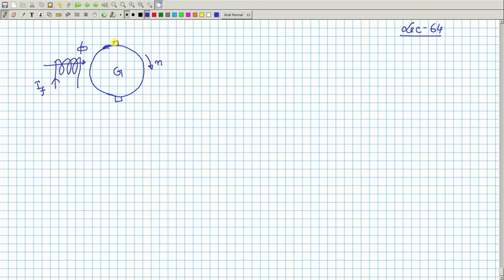Anyway, we found out that if this is rotated, in this case, the voltage across the armature terminals A1, A2 under open circuit condition, if I say generated EMF E g, it is given by P z by A phi into n, so much volts, if phi is in Weber and n is in RPS, do not forget that. Of course, it can be changed to RPM.